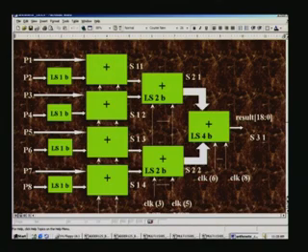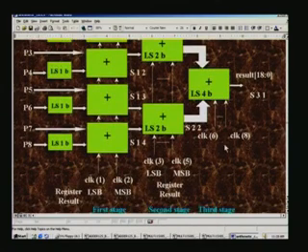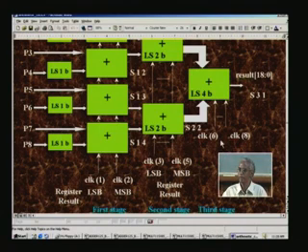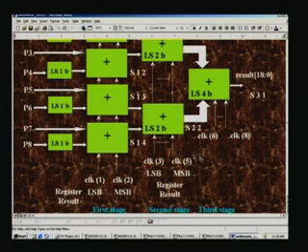You can experiment with this to see whether we can reduce the clock, and there may be some scope for you to reduce. Instead of 8 pipelines you may get even 6. In fact this is not really required, because what we are going to do is pipeline not only the multiplier but also the entire process. Even a complicated algorithm can be pipelined totally, and all these pipeline delays will only be a one time affair.